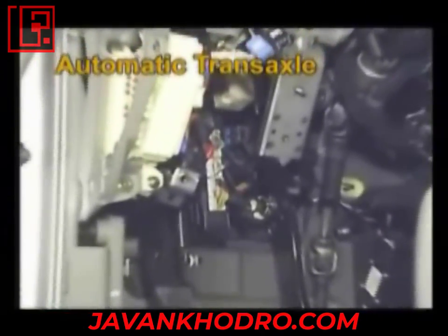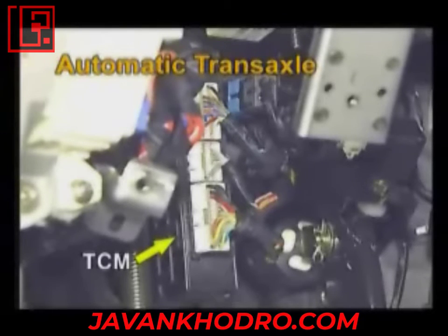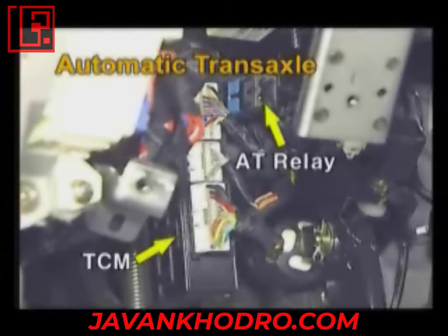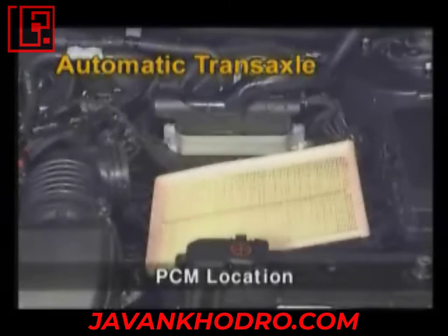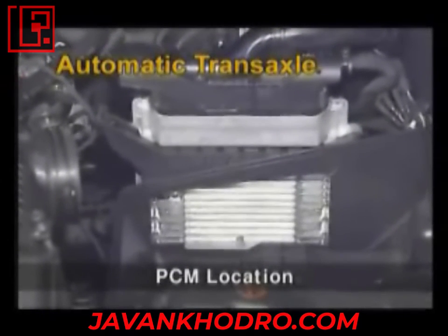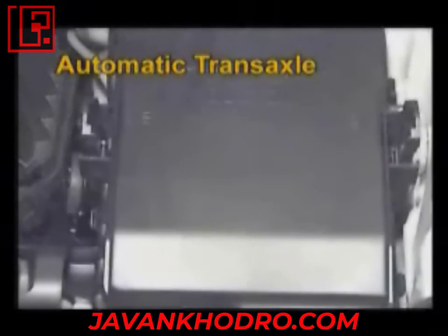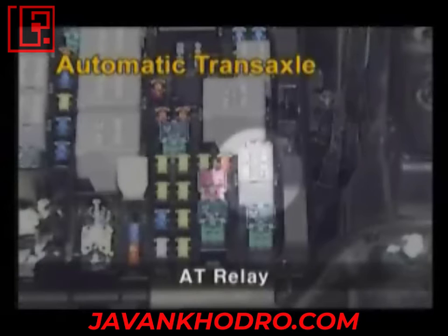For the installation position, the TCM of the 2.0-liter common rail diesel engine is installed under the crash pad on the driver's side. The AT relay supplying the electric power to each solenoid valve is installed next to the TCM. For the gasoline engine, integrated type PCM is used and installed at the engine compartment. The AT relay is installed in the engine room junction box.